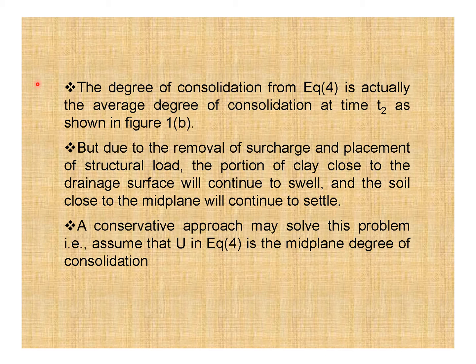The degree of consolidation from equation 4 is actually the average degree of consolidation at time t2 as shown in figure 1b. But due to removal of surcharge and placement of structural load, the portion of clay close to the drainage surface will continue to swell, and the soil close to mid-plane will continue to settle. A conservative approach may solve this problem, that is, assume that U in equation 4 is the mid-plane degree of consolidation.